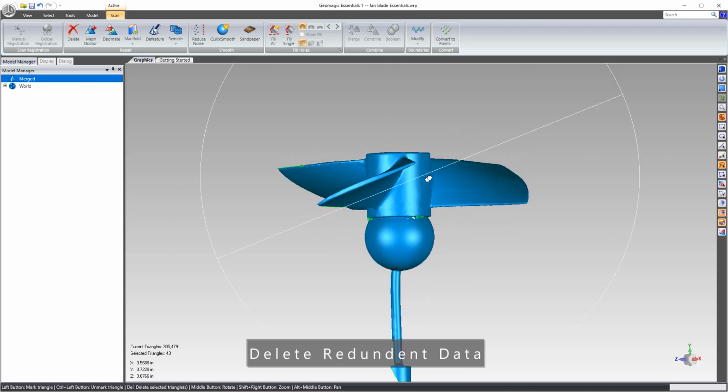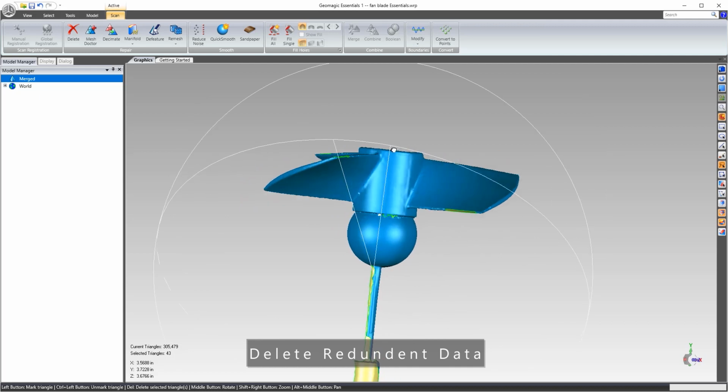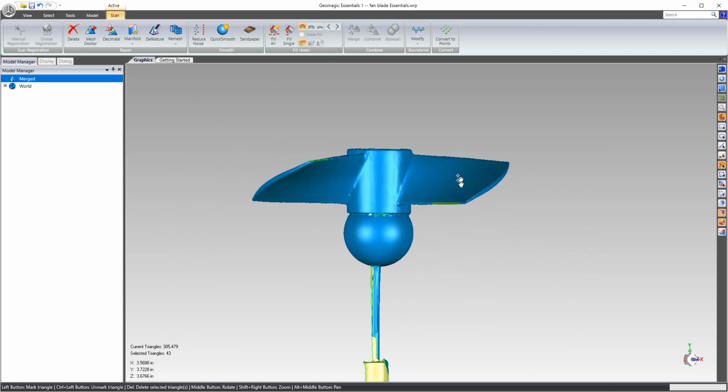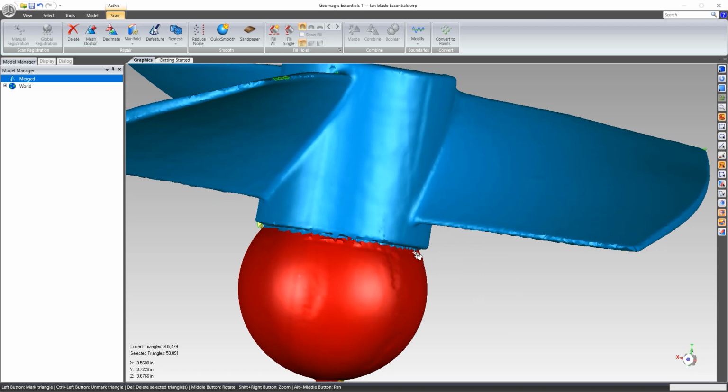So as you can see, I put the fan on top of this sphere. So if I want to remove that bottom area, I can just look at it from the side, and I can grab tools from on the right-hand side over here. In this case, the lasso tool, and then I'm going to change it over to select through. Now with this, I can come in and just window in and select through, and you'll see that it will go all the way to the other side.